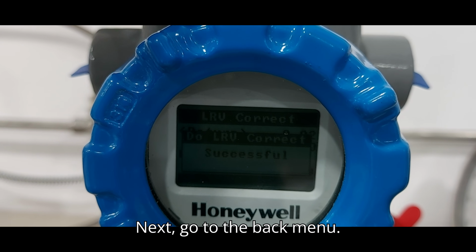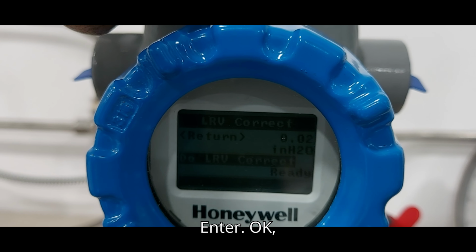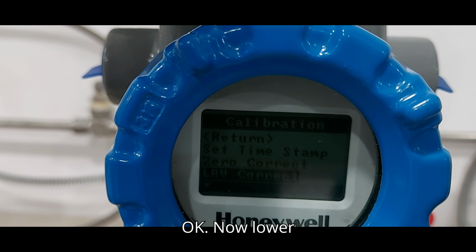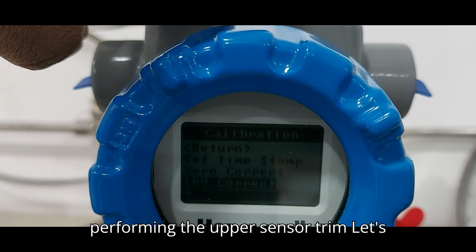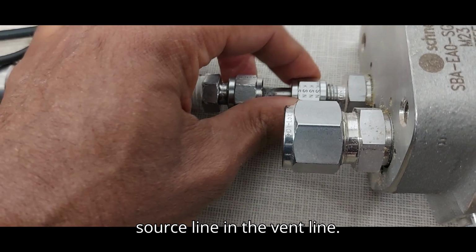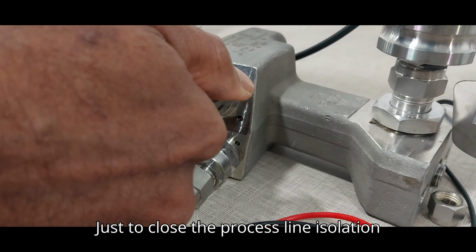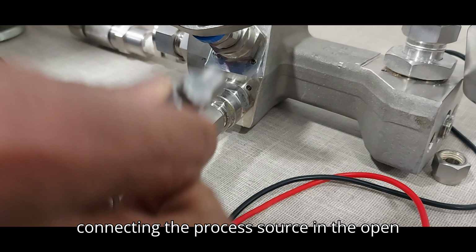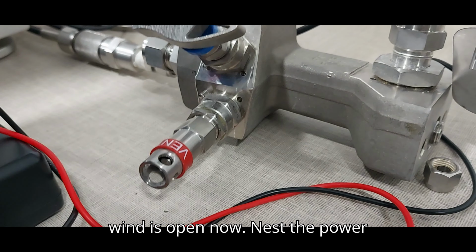Next, go to the back menu, enter. Return menu, select it, enter. Now lower sensor trim is completed. Next, we are performing the upper sensor trim. We are connecting the pressure source to the vent line. First, close the process line isolation valve. Next, open the vent line. We are connecting the pressure source in the open area, the vent line area. Vent is open now.